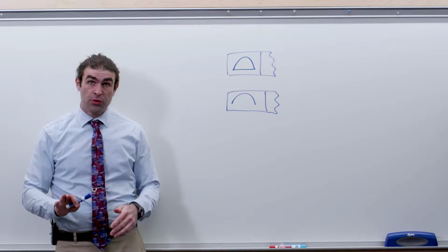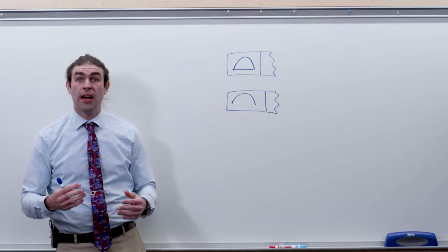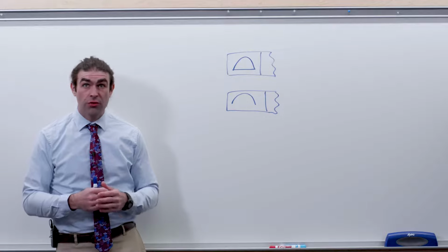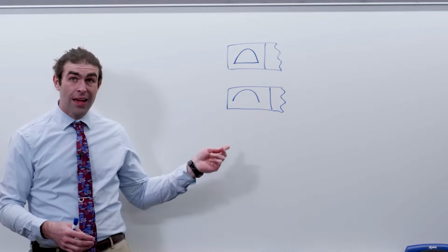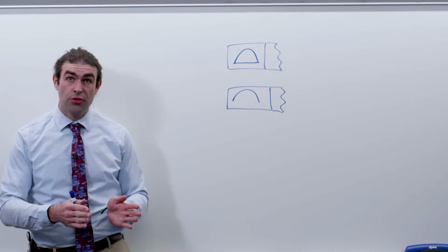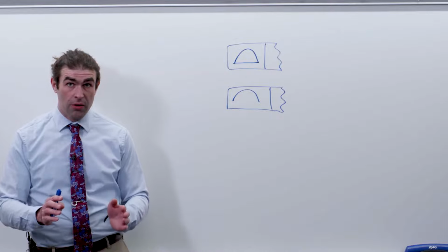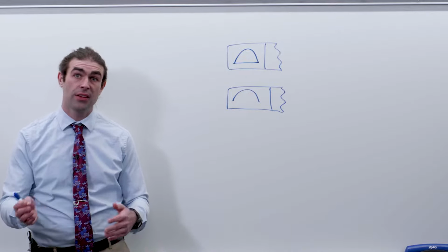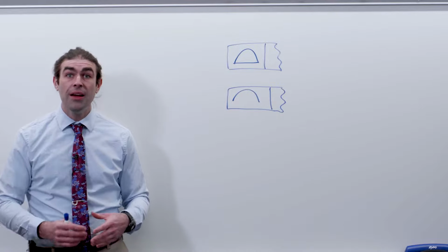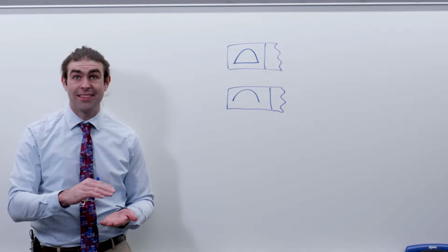Now, the difference between them is that profile of a surface is a 3D tolerance. What that means is it controls an entire surface, whereas profile of a line only controls individual cross sections. So a good way to compare this to something we've already covered is the difference between flatness and straightness. If you recall, when you apply flatness to a surface, it controls that entire surface.